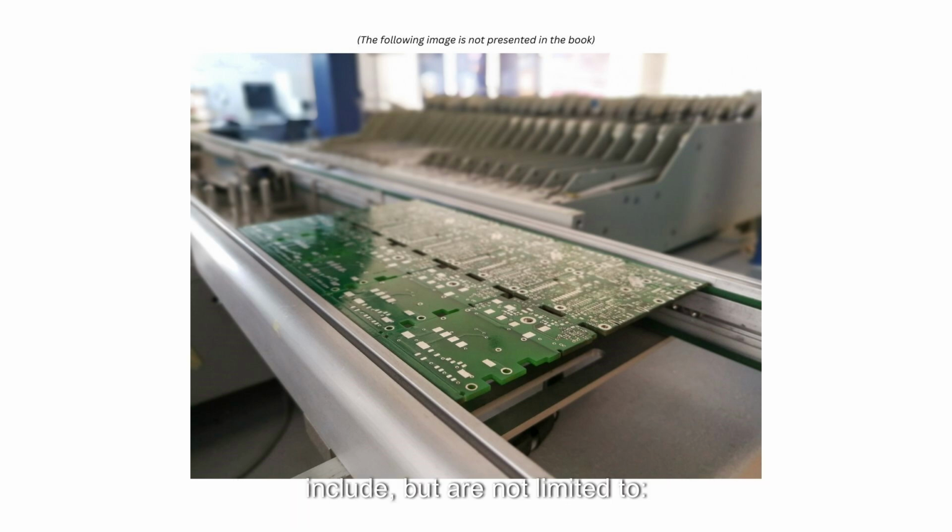These accommodations include, but are not limited to: device separation/spacing requirements, height restrictions, device alignments, test points. Fortunately, if one considers the needs of the assembly pick and place machines and the visual inspection in their design, the effort to accommodate testability already has a good starting foundation. Test equipment accessibility is the most significant issue when it comes to testing. This is not too difficult when the boards are bare, since there are no obstructions. After a board has been populated with components, the ability to test obviously becomes more difficult.